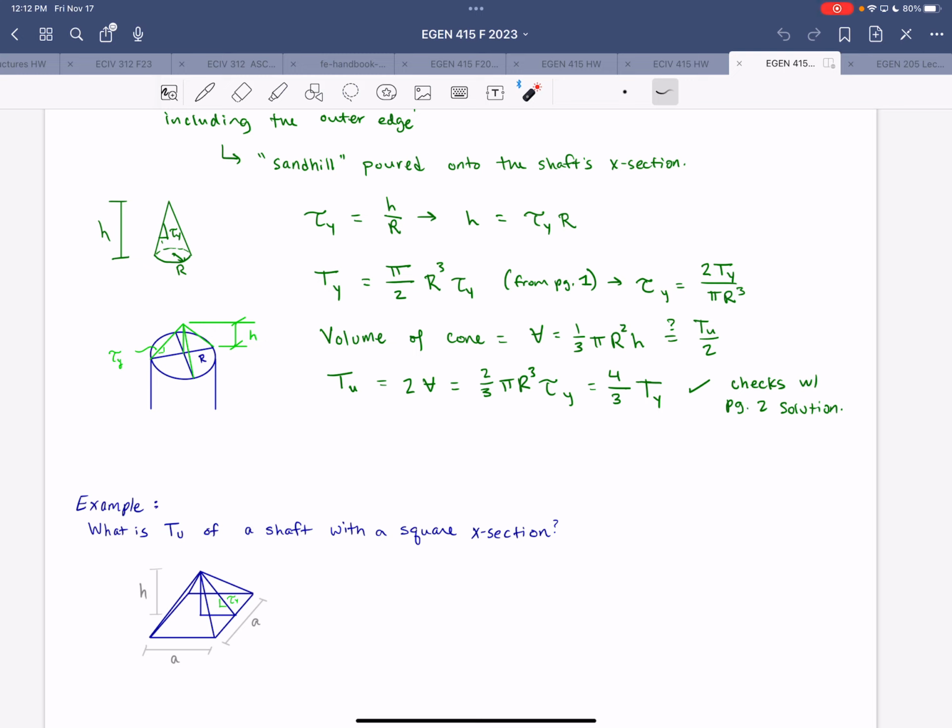If you take a cut and look, your material is going to be opposing the internal pressures applied to this surface. So figure out what that net force is and then distribute it to the material that's resisting it to get the internal stresses in these two walls.